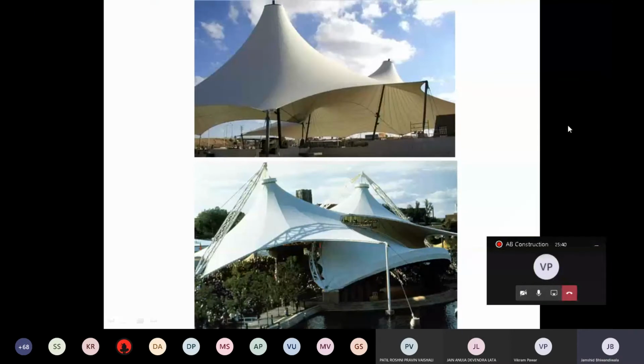I thought I'll show this diagram since we are talking about pivoted tensiles, to clearly indicate a pole centrally pivoted, or pivots from inside, vis-a-vis keeping the interiors support free. So the idea of pivoting the disc, from which the material seamlessly comes down, as you can clearly see. You can see the finish and the seamlessness in which the welding of the fabric has taken place.